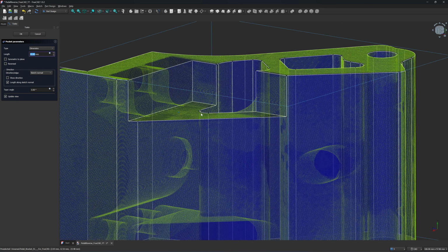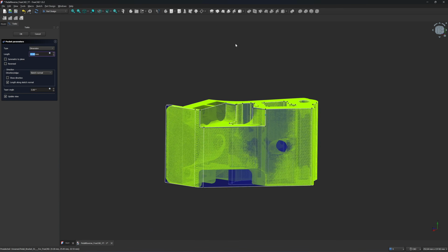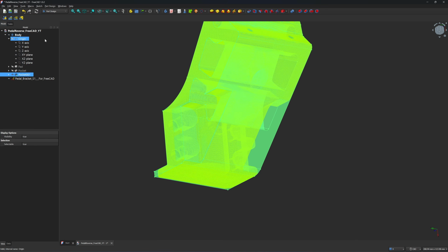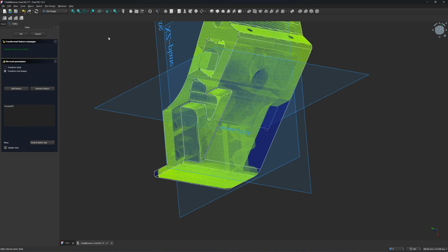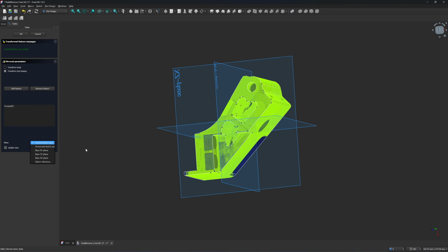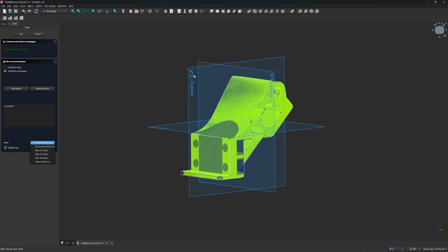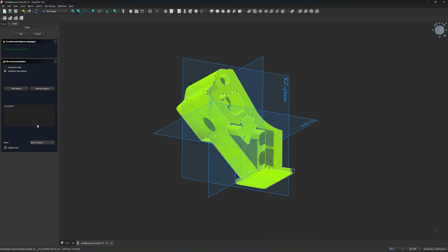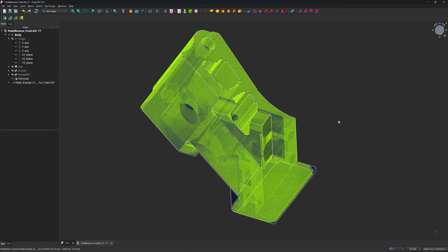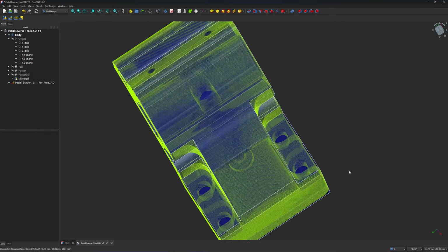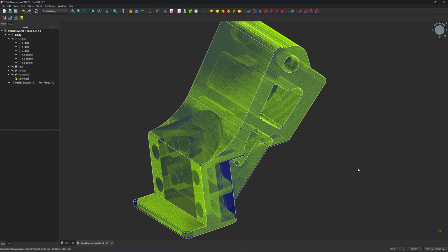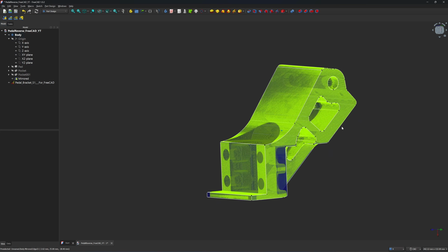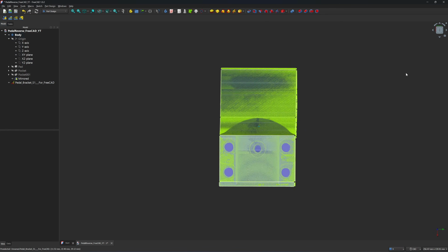Okay, now it's perfect. Here, 11 millimeters. I'm going to mirror this one to the other side. Click on here. Click on mirror command and choose the XC plane as the mirror plane. See now, this side is all cut. Click on OK. Okay, now you can see that this side is also cut because we pressed the point cloud in the center.